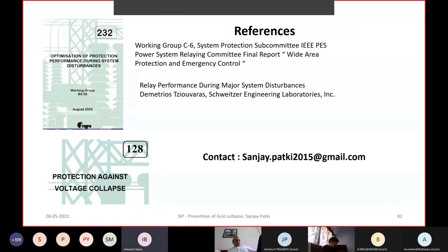Sir, I have a question regarding transformer protection. Can I go ahead, sir? Yeah, go ahead. Actually, sir, because the protection system has become very modernized now, the transformers are fully equipped with differential protection and REF protection. Now the devices which are there, like the Buchholz, the OTI and WTI. There are many instances of mal-operation of these Buchholz relays, tripping of the units due to Buchholz or some other devices. As we know from the principle, the Buchholz trip operates due to some major faults. So when a major fault happens, apart from the Buchholz, some other protection will surely act, like the differential or the REF. So can I combine the Buchholz trip with some other electrical protection, to prevent any spurious operation of the Buchholz?